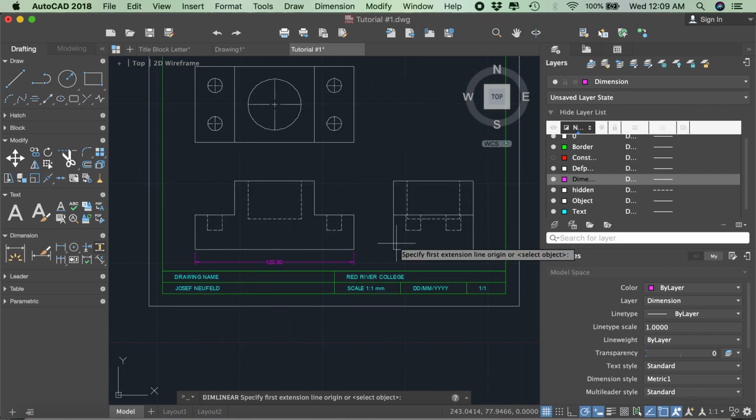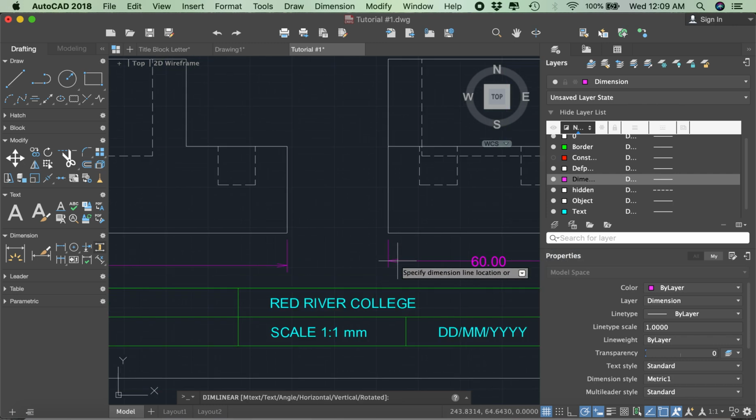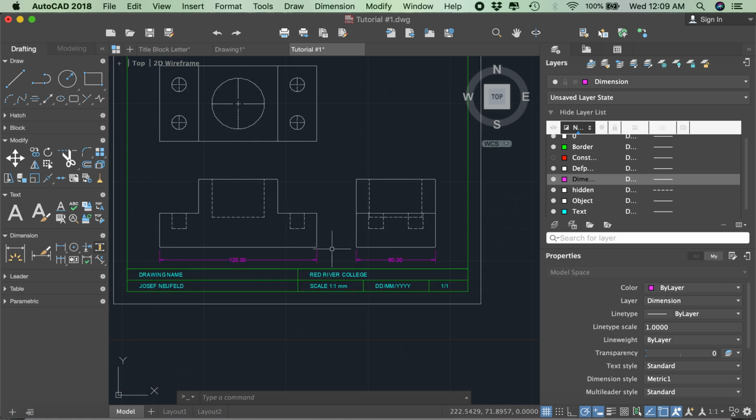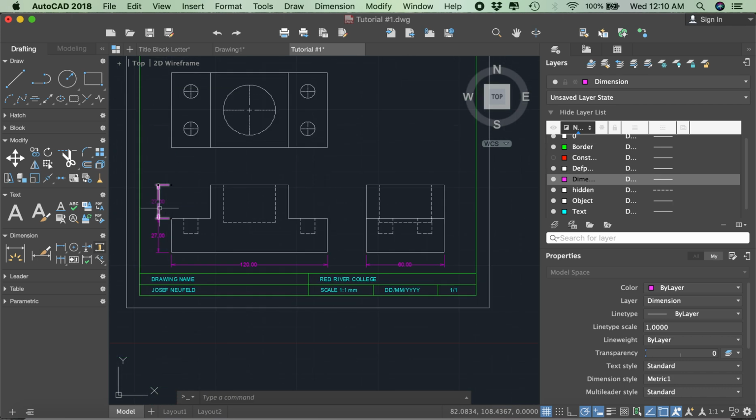Let's go ahead and add the width. As you can see, we could either hover over and drag down, type in 10, or if you have dimensions in line, you can just simply click on a point on that dimension and it'll pick that in line. Let's go ahead and put on a few more dimensions. We'll do the height of the lower layer, and we'll do the height of the higher layer. So as not to have additional conflicting lines, we'd like the dimension line to start from this outer point, and we can select this point to have it line up perfectly.